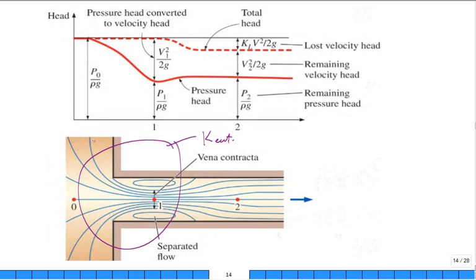Well, try and draw a bunch of streamlines for the fluid. And the fluid that starts kind of out here and just gets into the pipe, it just goes on a nice and easy trajectory. But what about the fluid packet over here, over here, over here? Well, they're not logically going to start in the center of the pipe, but nearer the center and closer to the edge, closer to the edge. And what happens is the fluid packet that comes this way really has to take a sharp turn. And fluid doesn't like sharp bends or kinks.